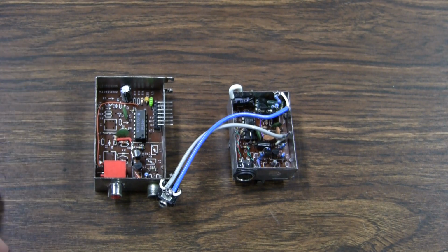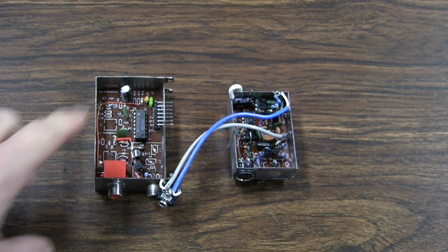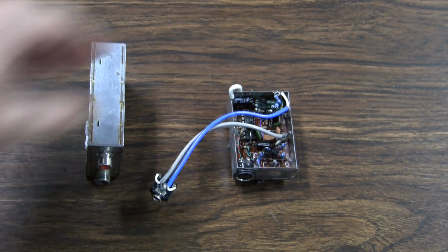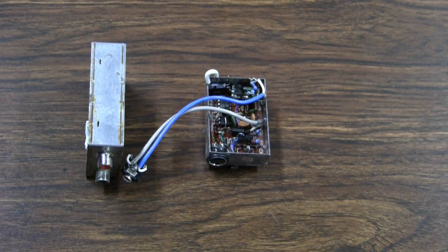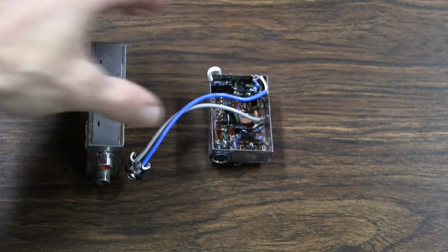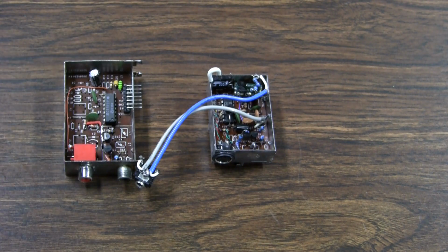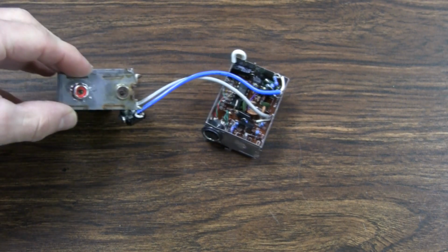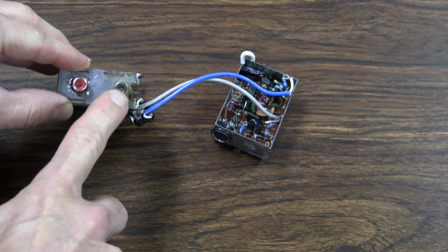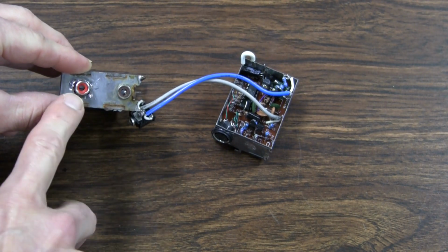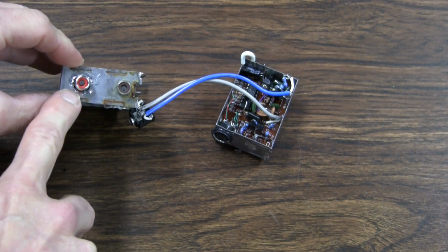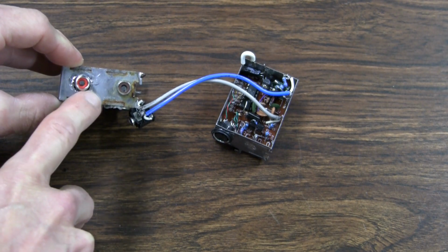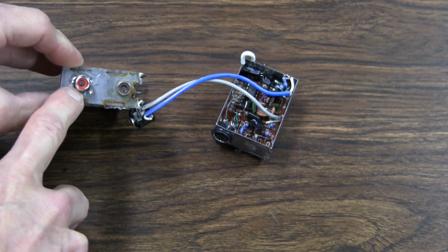And here's a view of the two modulators with the mods in place. This is the older modulator that actually is mounted vertically on the PCB like that, and then this is the newer modulator, which is quite a bit smaller, and it's mounted horizontally just like that. Now let's take a look at the new connector layout. So this has been left alone, so this is the composite video out, and I've removed the channel selector switch from the PCB and then rounded out the rectangular opening and soldered a new audio connector in place.